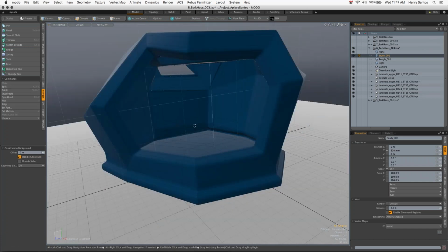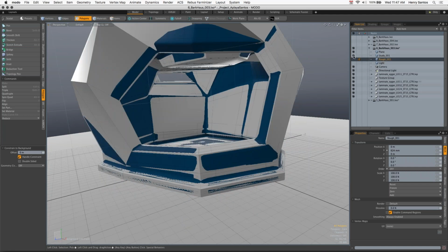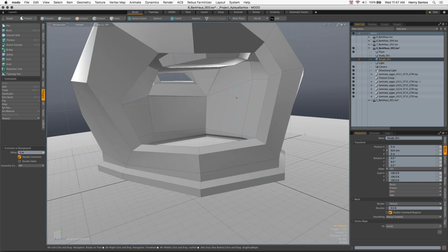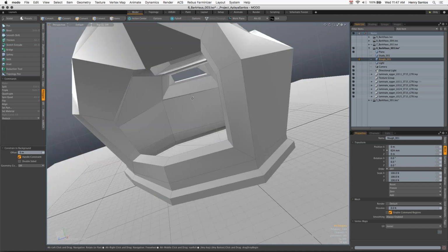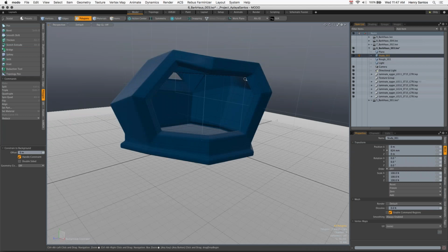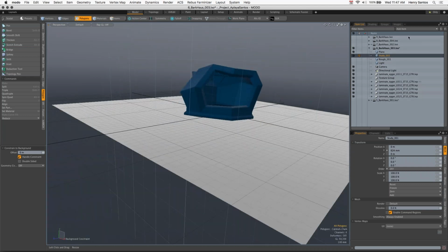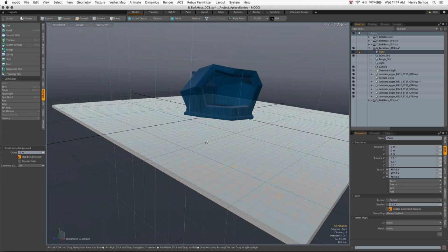And the difference with this and that rough model, besides the new crazy look, is, oh, actually, you know what? This one was thickened. You can take a polygon like this ground plane and add thickness to it. So, let's say 10 millimeters, and say apply, and it thickens up the model.